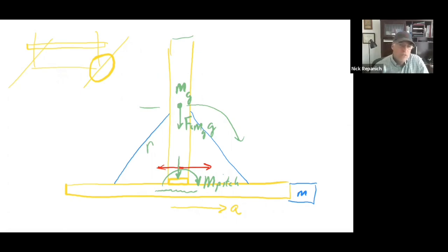A lot of times on this, you don't know the exact answer. So what you do is you take the worst case. Worst case would be when you have this cross axis and the extruder way up at the top, which puts the mass way up there. Now this force is larger. The mass is way up here, so the radius got larger. So therefore, the pitch moment on this bearing down here is going to be worst when you move the load to the very top.